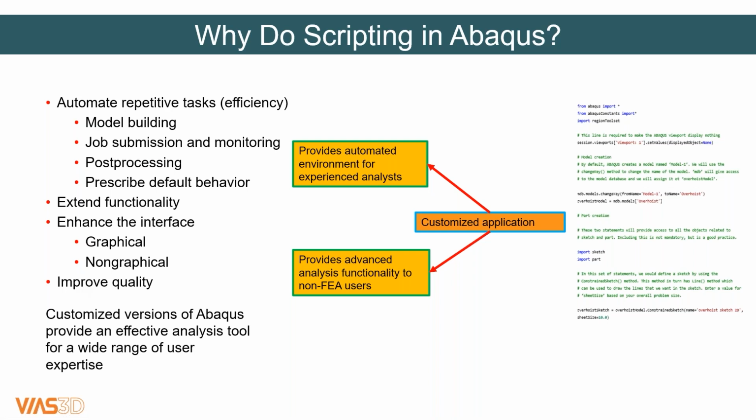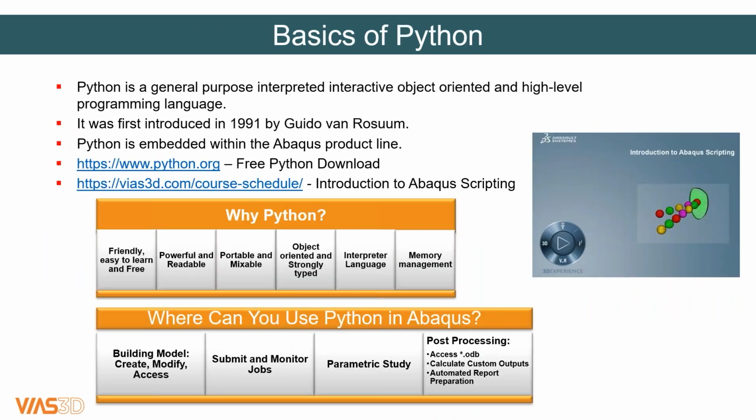If you have a lot of repetitive tasks, it's definitely more error prone. If you can create some type of script or interface that is verified, then you take a lot of that out of the equation. So in order to do scripting, Abaqus has two APIs, one for the GUI toolkit and one for the scripting interface, and you need to know Python to work with it.